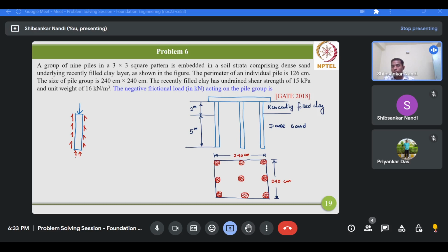However, one point is to be noted here: in this mechanism we have considered that when the pile is subjected to some axial vertical load, the movement of the pile relative to the adjacent soil mass is greater, and it is in the downward direction, and it's obvious.